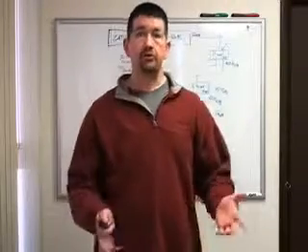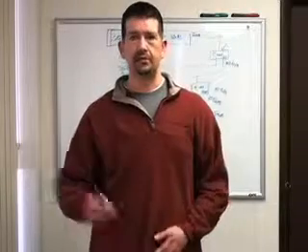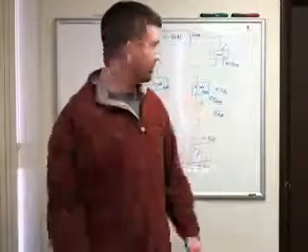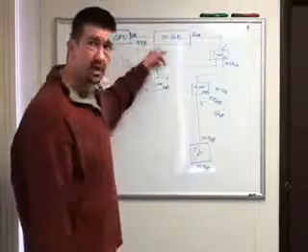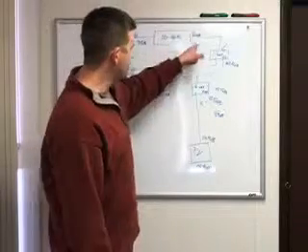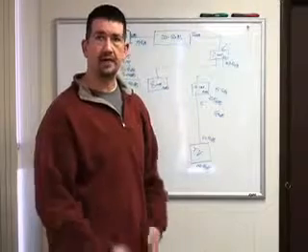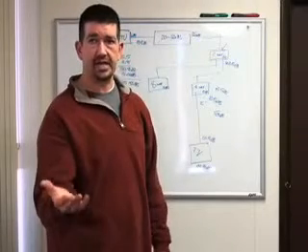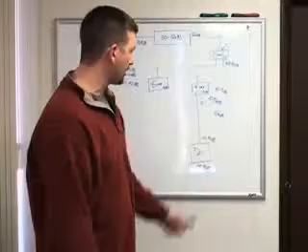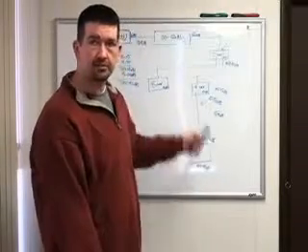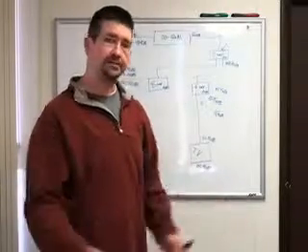When you have to go out and troubleshoot a system, and you don't have signal at the end, you want to be able to start at the cable company, measure here, measure here, measure here, start going through the system and find out where you're losing the signal at. If you have a signal meter, it's going to take you half an hour. If you don't have a signal meter, you're going to have to go through and replace wire, replace cable, until you figure out what the problem is.